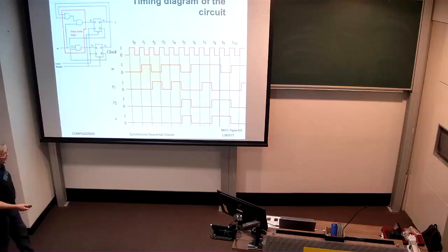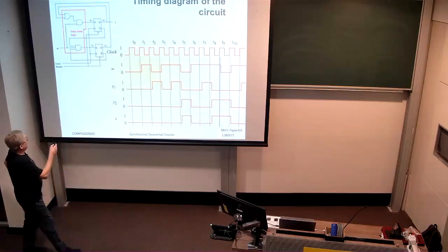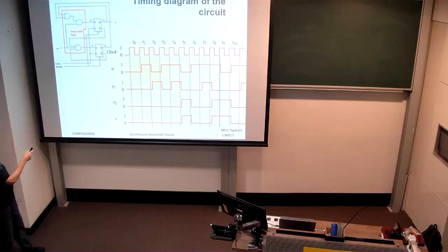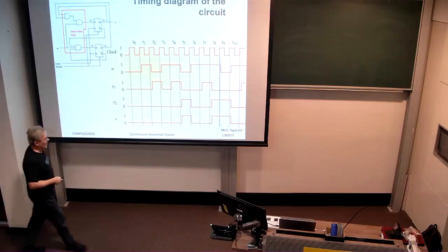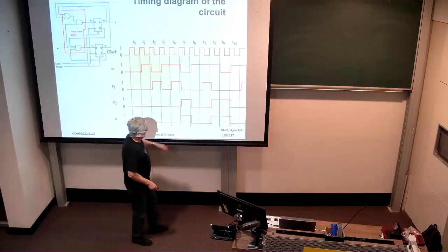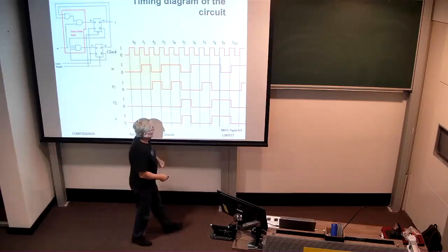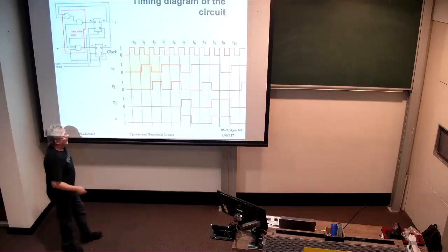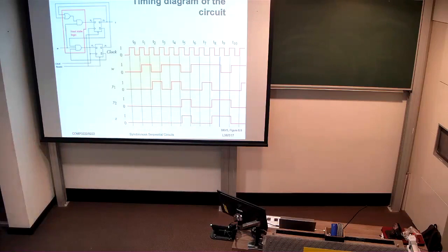We see a third W, which is really just recycling the Y2 being 1 now up the top here. So we stay in that state 1, 0, and our output stays high. But on the next clock edge, we see that the input W is low, and therefore the whole system resets itself again.